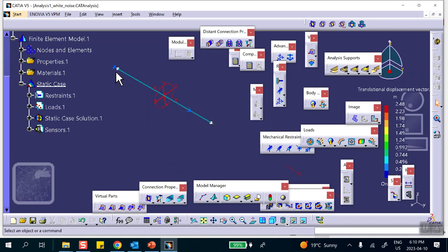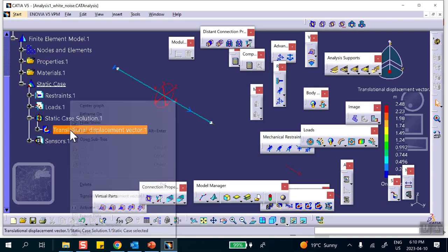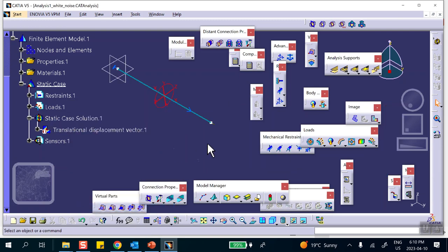Now, if you go and make those Young's modulus and things like that perhaps smaller, you're going to get closer to 2.5. But one thing I want to do is deactivate this plot, and I want to apply a restraint here so that it only moves in the direction y.